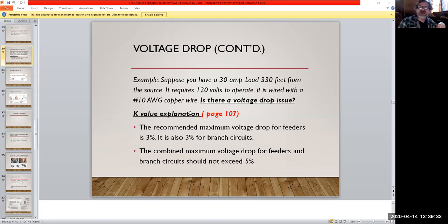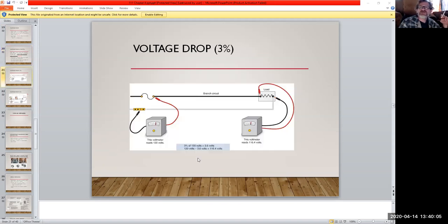So instead of number 10, if it didn't meet what you needed, you would end up running number 8 because it would have the greater ampacity, right? Then it would be able to deliver, and it wouldn't fall under the rating it needed to be. So always take this into mind when you have a really long run. You never know, somebody's house might be shaped so weird that you have a really long wire run. You would have to resize it, and you could check it.